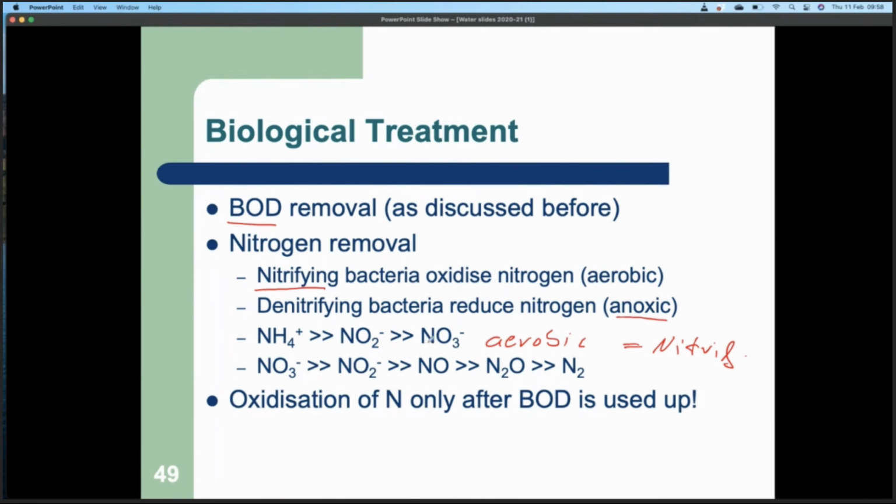So in terms of fertilizer removal, you have not achieved anything by oxidizing in an aerobic treatment ammonia to nitrate, because you still had one atom of nitrogen, and at the end of the whole treatment you still have one atom of nitrogen, and it's the nitrogen that is the fertilizer. It's not the oxygen or the hydrogen. So you haven't achieved anything.